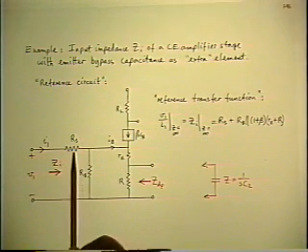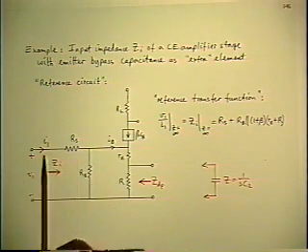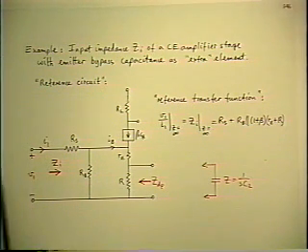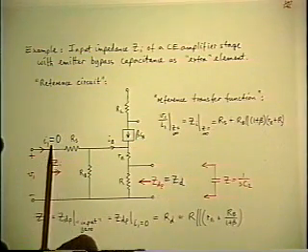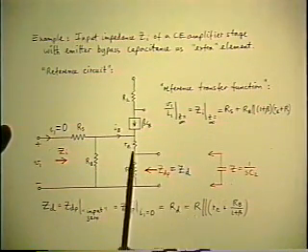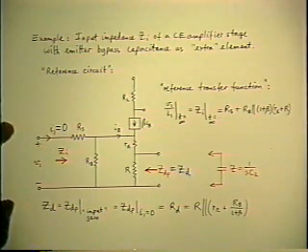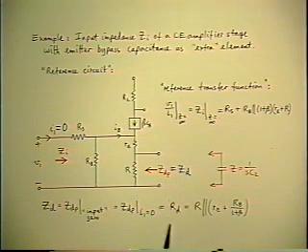Only RB. The RS isn't going to come into it because RS is dangling. The other end is open when I1 is 0. So the condition for ZD is I1 is 0, which means an open input, and the answer is R parallel RE plus the reflected RB.